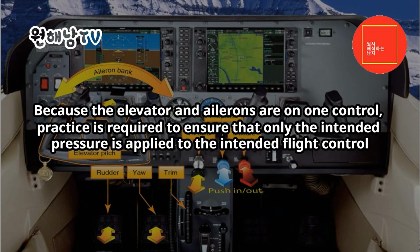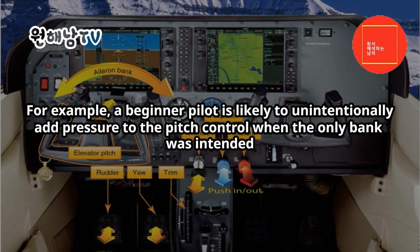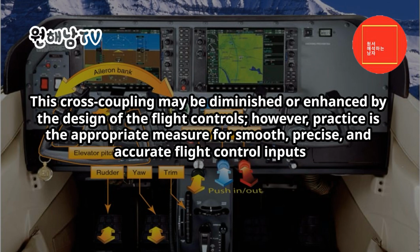Because the elevator and ailerons are on one control, practice is required to ensure that only the intended pressure is applied to the intended flight control. For example, a beginner pilot is likely to unintentionally add pressure to the pitch control when only bank was intended. This cross-coupling may be diminished or enhanced by the design of the flight controls. However, practice is the appropriate measure for smooth, precise, and accurate flight control inputs.